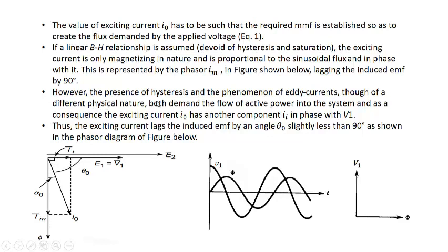However, the presence of hysteresis and the phenomena of the eddy currents, though of different physical nature, definitely will not be of the same nature as a resistor. That means they will not lose the power in terms of heat as is done by the resistor. They are doing that in a different manner. But we'll take it as if it is doing it in the form of a resistance.